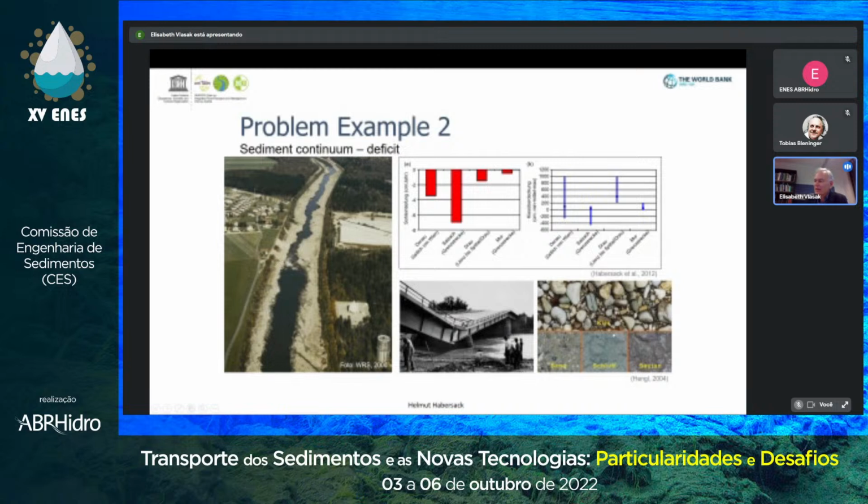You know, this is just a schematic drawing. Now this means in many rivers you have gravel somewhere, or sand, or whatever it is, and you have finer material, in this case sand, also silt and clay below there. Now the issue is that this might be only a few meters, 10 meters, maybe even 20 meters, but you have a certain erosion rate, like you see it above here in centimeters per year.